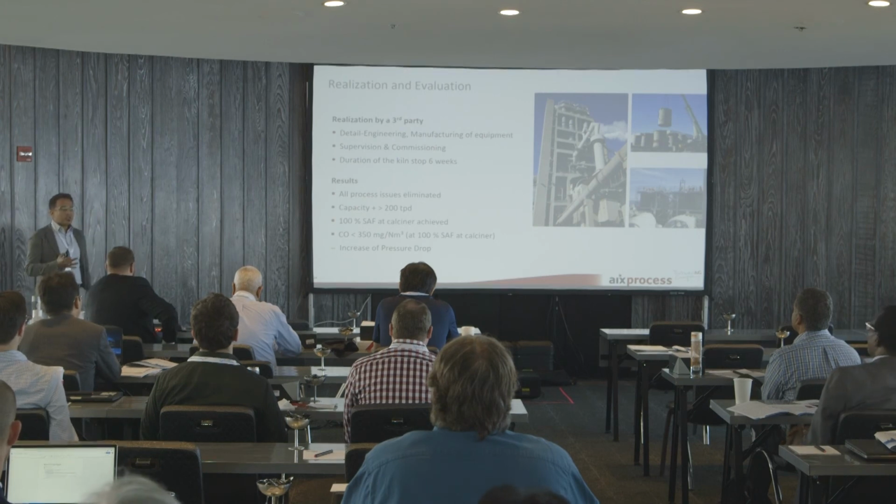We could increase the capacity. Now the secondary fuel rate is at 100%. So this is one goal, and we still match the CO emission. So this is really a success story. All the engineering was done up front, so there was no trial and error, and the duration of the stop was just 6 weeks. So this is a rather typical stop during summertime, where they typically do the revamping.